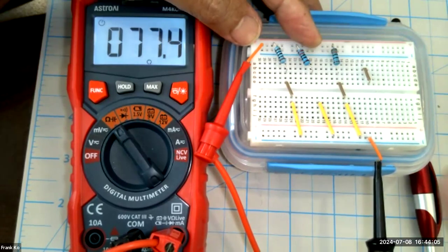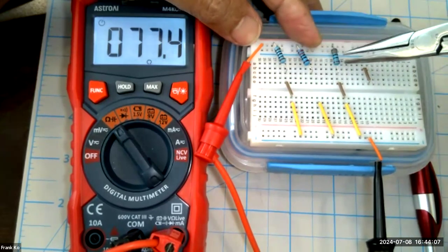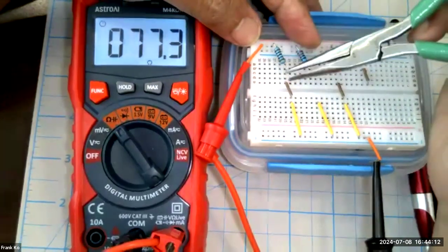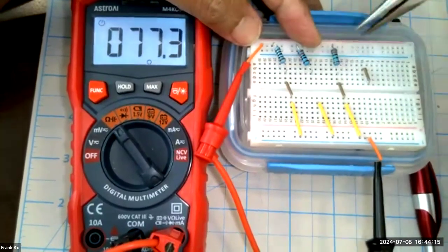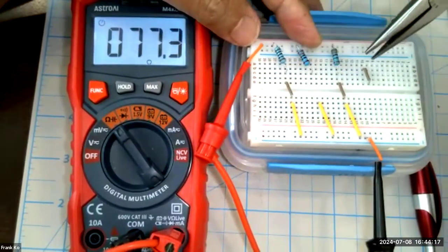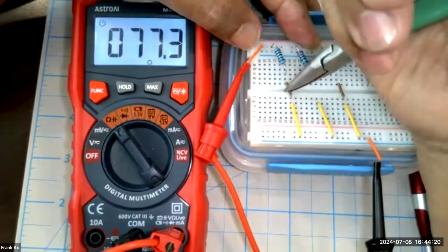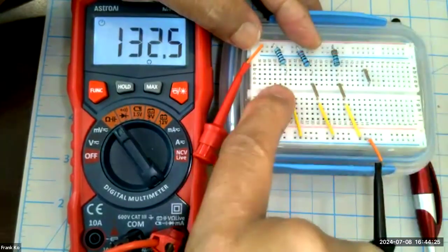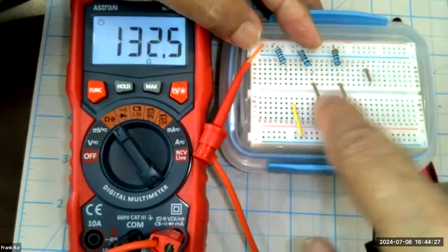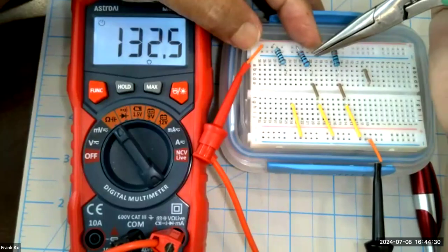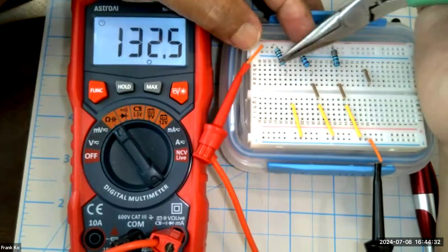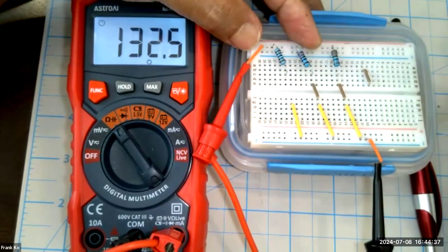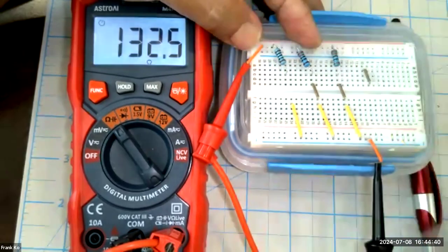All right, the third scenario was R2 parallel with R3, presuming something was wrong with the first branch. Either the resistor burnt out or the wiring was wrong. I can very easily test this because I've done neat wiring on the board simply by moving one jumper, positioning this from here to here. Remember, if I have one fault condition, which is an open here, I have to rebuild the rest of the circuit. So do I now have R2 parallel with R3 only, and R1's no longer part of the circuit? What did we calculate for R2 parallel with R3? Your notes say 132 ohms. What do we measure, my friends?